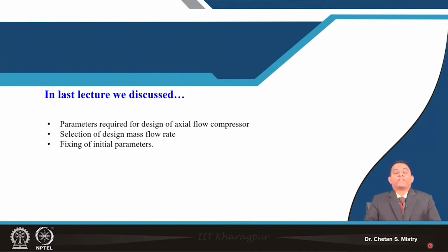For middle stages, our expected pressure ratio is moderate, but efficiency is on the higher side, because of the flow uniformity we achieve in the compressor. For later stages, the blades are shorter, which gives flow three-dimensionality, leading to increased losses and reduced efficiency, and the expected pressure ratio is on the lower side.